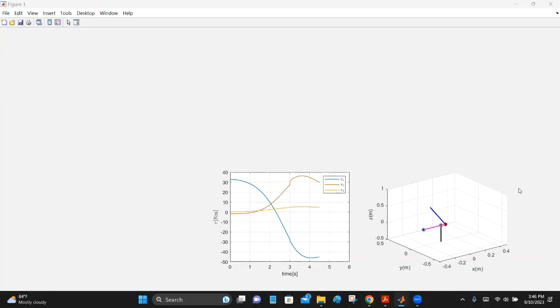Now, because of the decelerations, right, the velocities some of the joints have got earlier are now reducing. So therefore, motion is slower now. And also because of the negative acceleration initially, one joint got a high velocity in negative direction. Now it is also getting near to zero, right? So therefore, you will not see fast motion on the manipulator right now.